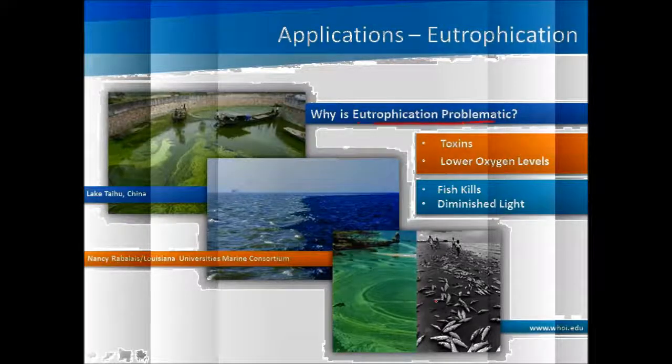The first is one I touched on earlier, and that is some algae species produce toxins that make the water dangerous. So this can obviously impact humans and animals ingesting the water. The second problem is the increased algae can lower oxygen levels. This happens once algae die and decompose. The microorganisms devour this dead algae, producing anoxic water conditions. The third issue is a consequence of the last, as these low oxygen levels can suffocate the fish.